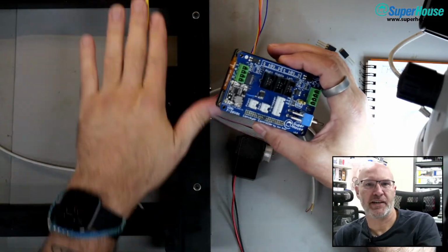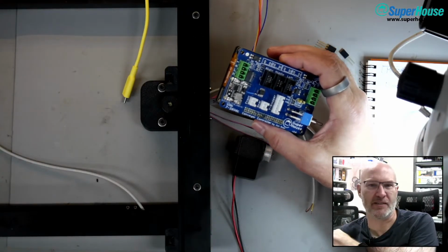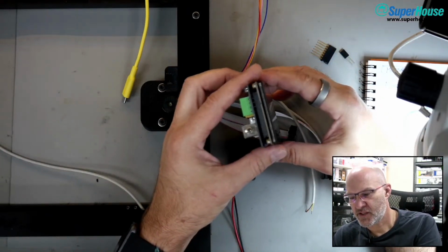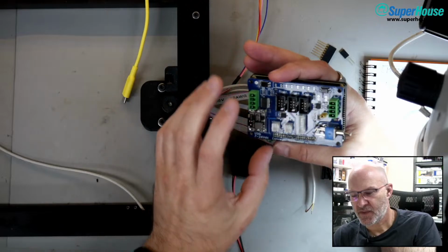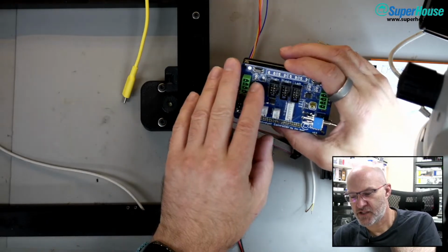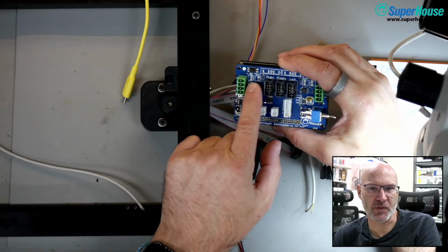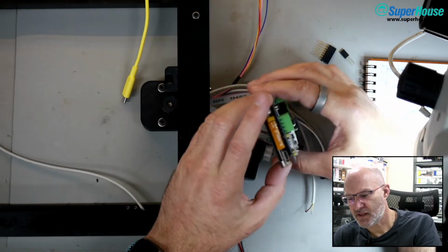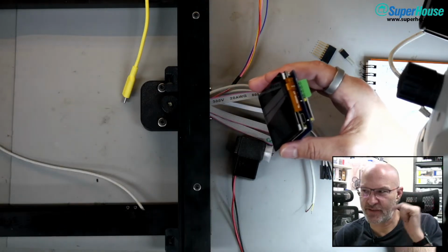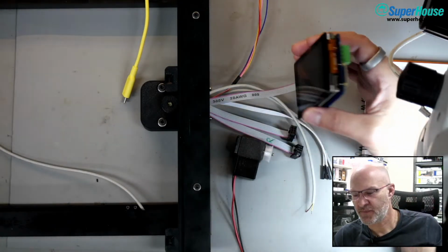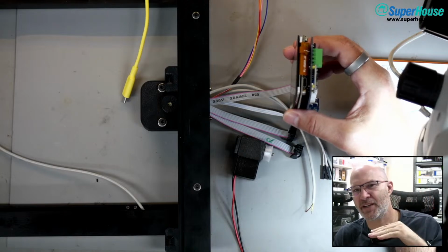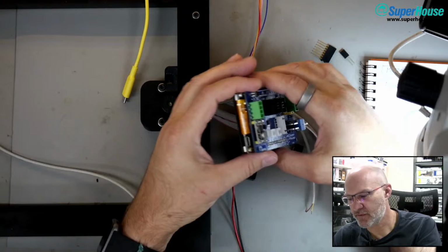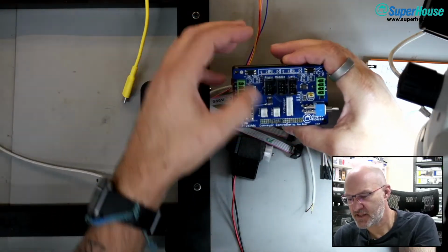This can then start the conveyor and move the PCB onto the pick and place machine, onto its conveyor. And conversely, when it's on the output side of the machine, it will be asserting its own ready in to say when it can accept a board, and it'll be watching for the pick and place machine to assert its ready out, and when one is ready to send and the other is ready to receive, they both activate their conveyors and they run the board from one to the next. So as you can see, that isn't even populated.